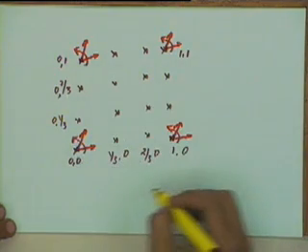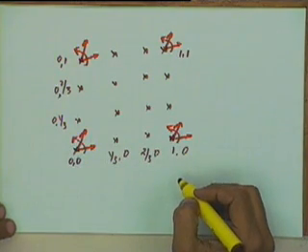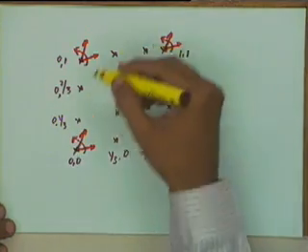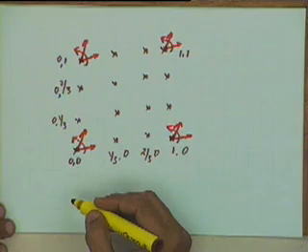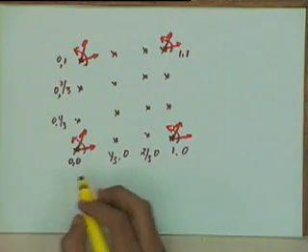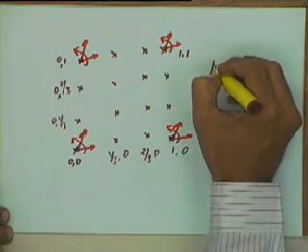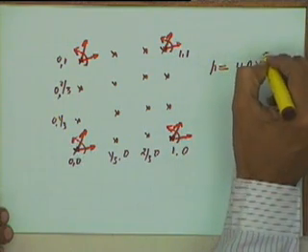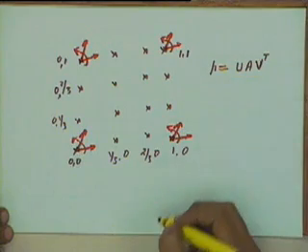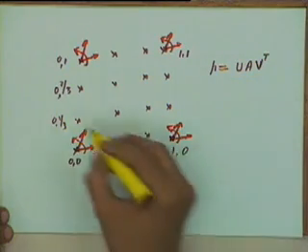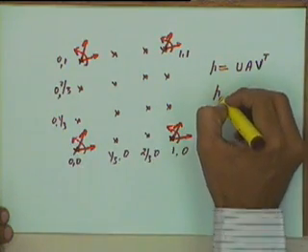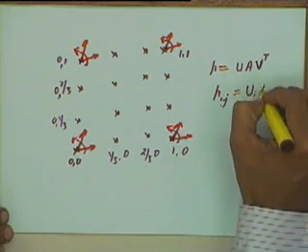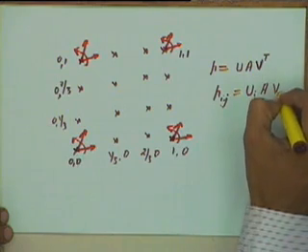If we give the input as these 16 points, and we say that this bicubic surface patch should pass through these 16 points, in that case again we can write down, we know the equation of the surface as P is equal to U A V transpose. At each of these points, we can write down Pij as Ui into A into Vj transpose.